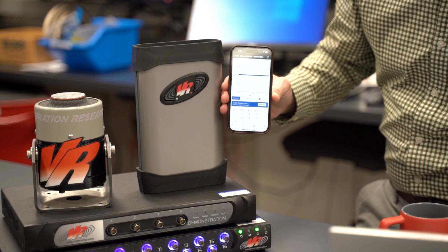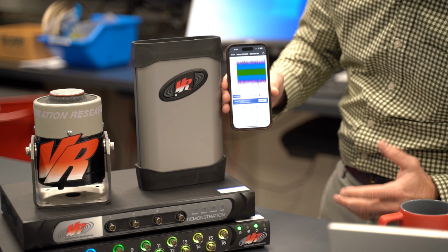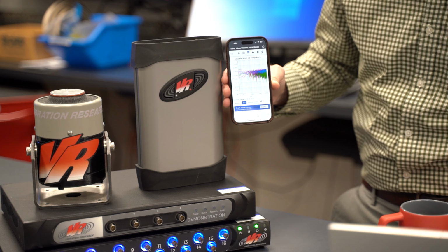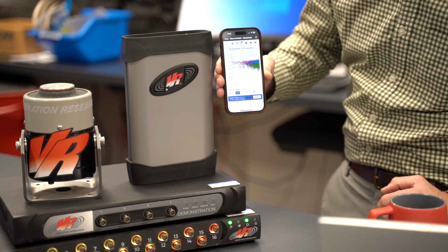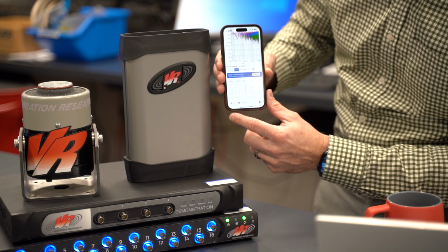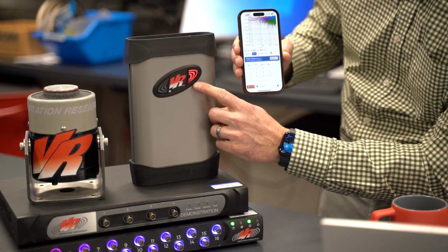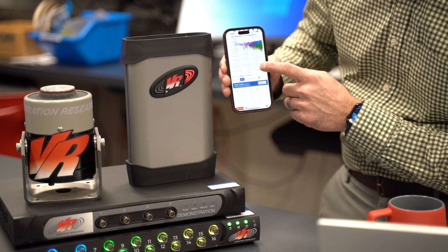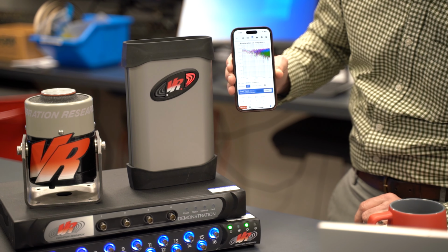So now as it loads, now I can see what's happening live. I don't have anything connected to it right now, but I can see waveform and the FFT of all of the channels that I have on this device. So waveform and FFT is a nice way to see what's happening. And then what I can also do on the app is hit the record button down here, so I can record remotely, starting and stopping recording on the device. And now I can see that happening both on my hardware as well as in the VR Mobile application.